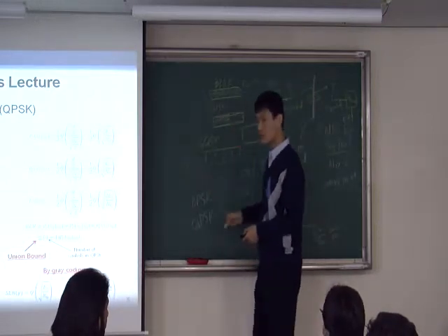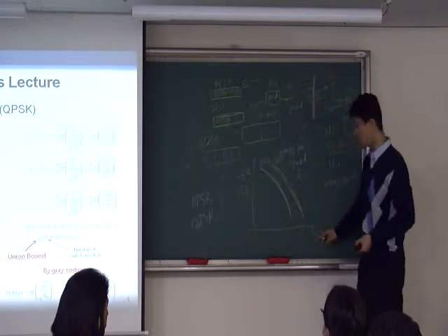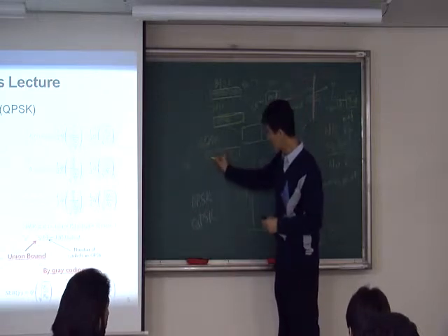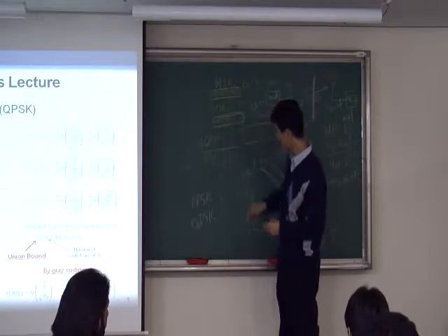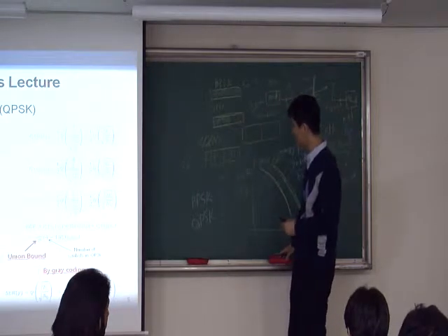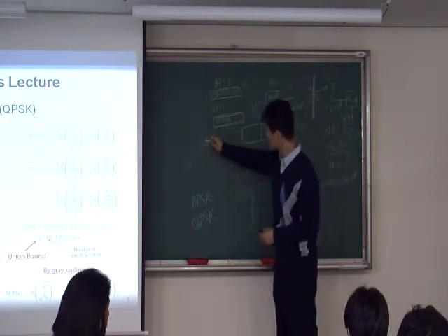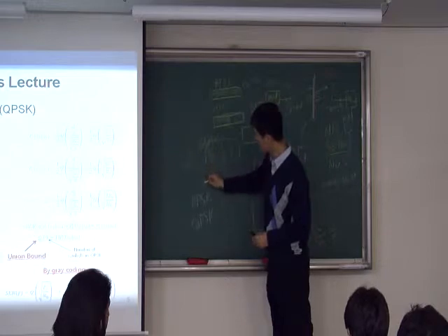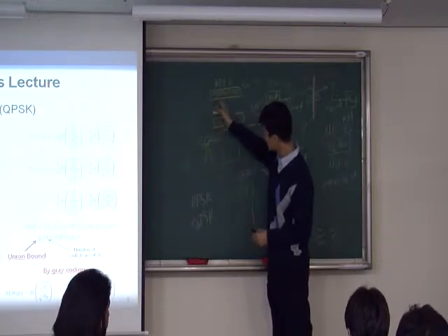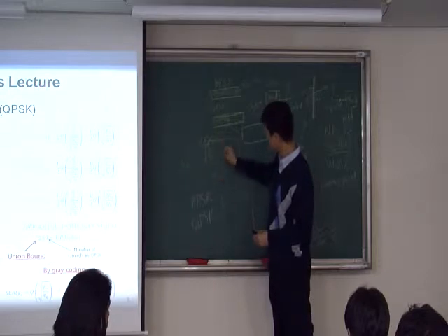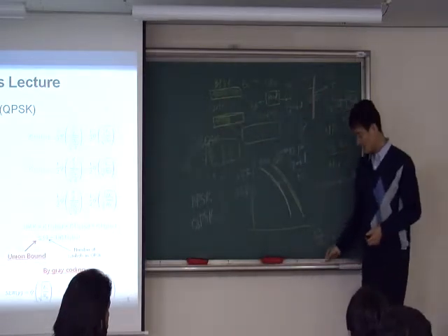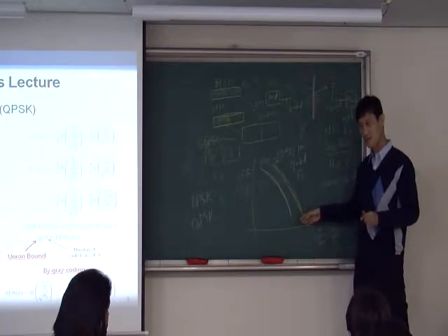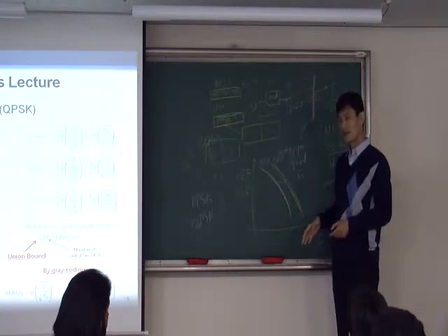So it's the same way. If you want to find out the BER versus EB over N0, then again, I fix the EB. Okay? So in that case, this EB should be the same as this EB in order to make a fair comparison, in order to see the BER versus EB over N0. So therefore, if you think about ES, since I fixed the EB same as this one, ES for this guy is going to be 4 times ES of this guy, right? So in that case, it's not going to be the same, in fact. It's not the same, actually. Why is that? Even though you fix the EB...